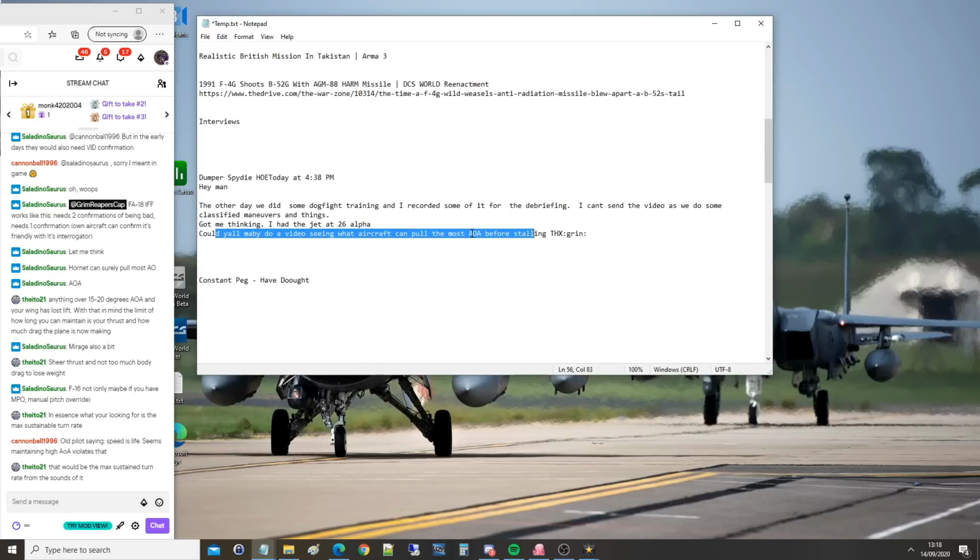For instance, if you've got, say, an F-14 with 26 degrees per second turn in optimum condition, fighting a Spitfire with 26 degrees optimum turn, so they both turn around the circle at the same time, but the Spit can turn in 500 feet radius and the Tomcat needs 2,000 feet radius, the Spitfire will win because it can keep inside of the turn and therefore it can still control the fight. There's very little, in terms of knife fight, I don't mean extending and going upwards and stuff like that, but pure knife fight, pure circle fight, then the Spitfire can win that.